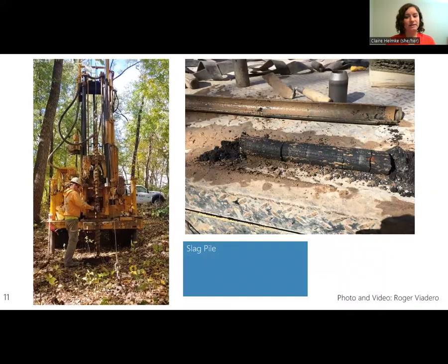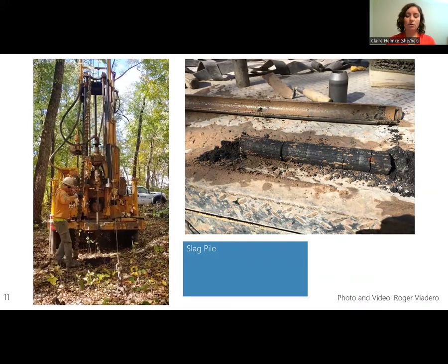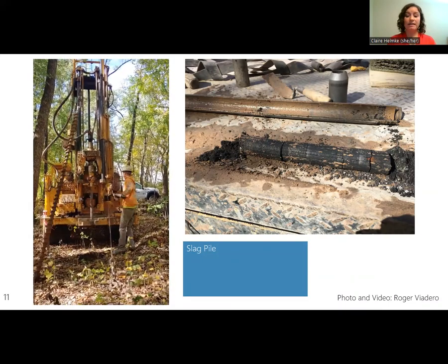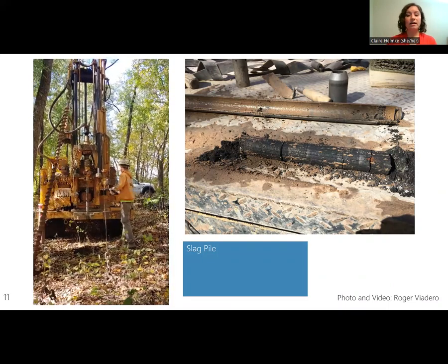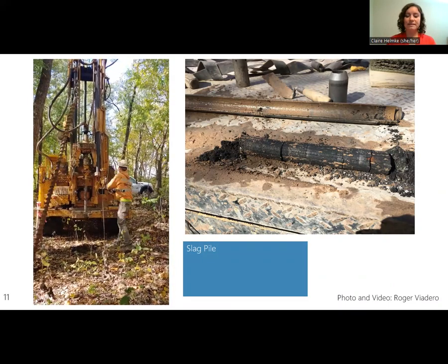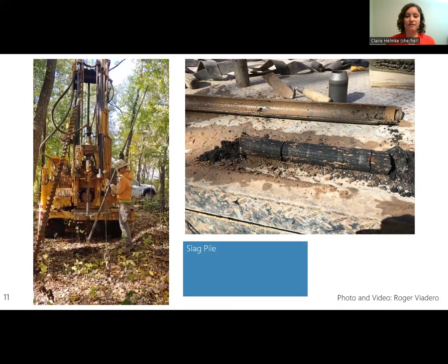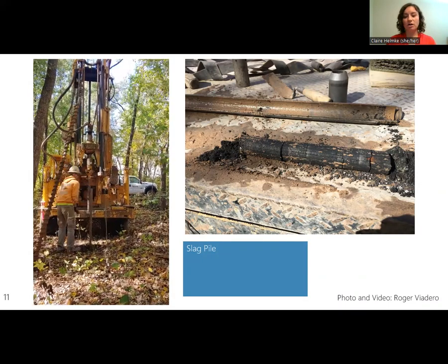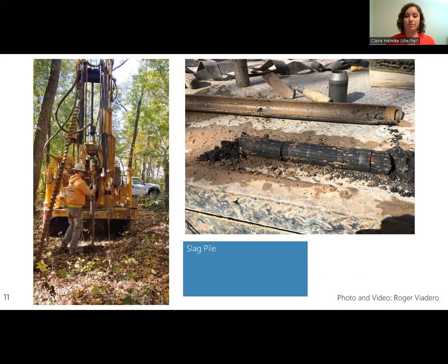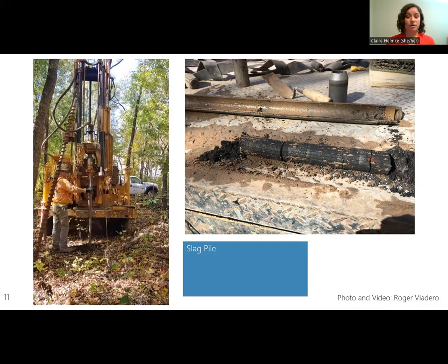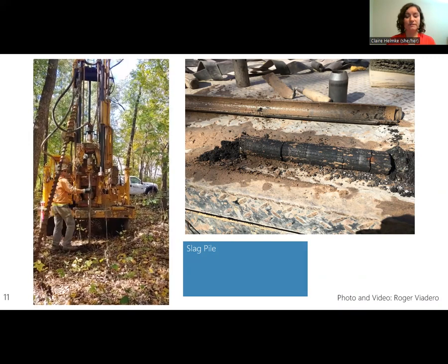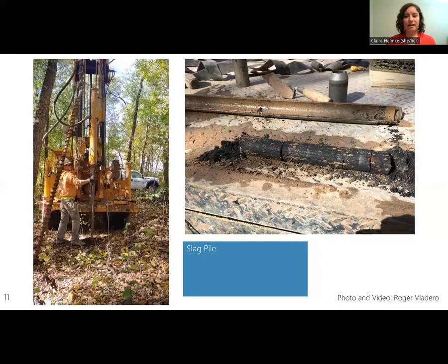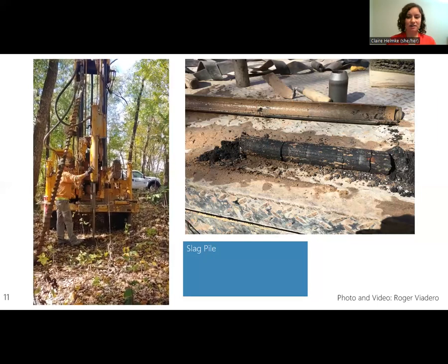To accurately estimate the size of the slag pile, 4 soil bores were collected from around the estimated perimeter of the slag pile and the estimated highest point of the slag in October of 2020. These locations were decided on by the evidence provided from digital elevation models from LiDAR and the presence of large slag boulders around that part of the property. Looking at the soil horizons from the bores around the perimeter of the slag pile, you can tell the difference between the dumped foundry slag and the native sand based on just texture and color.